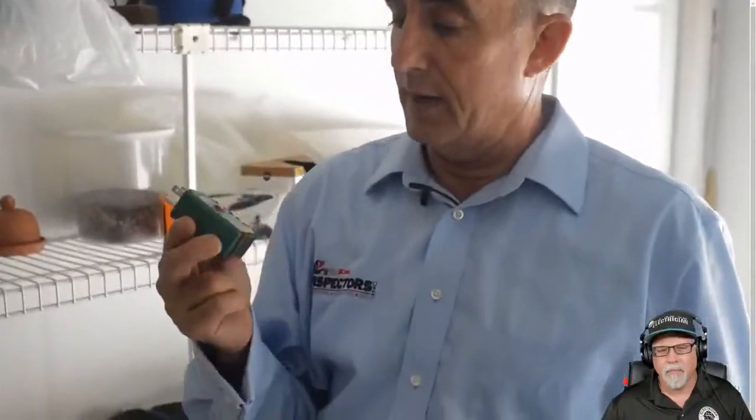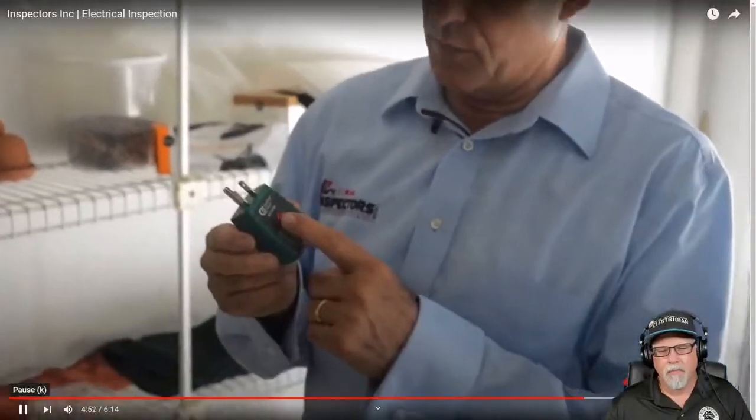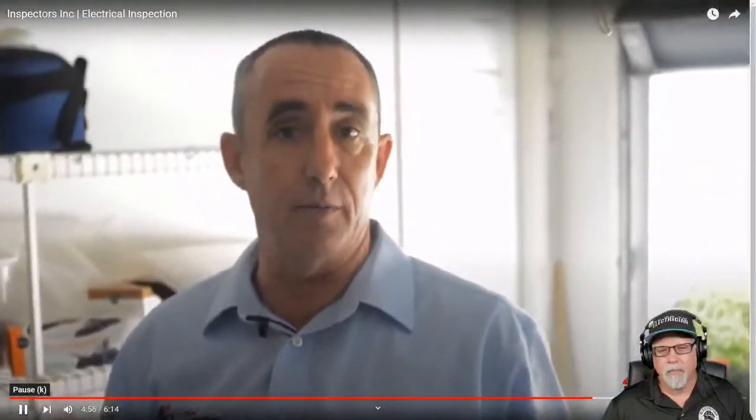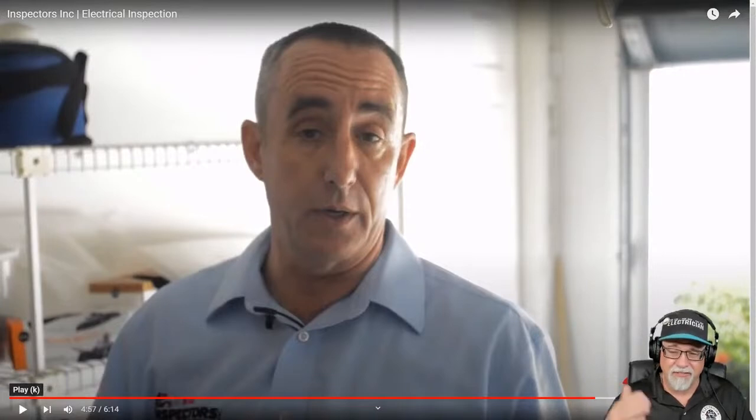Okay, so the next thing in the electrical system that we check is the actual appliances, or the lights, the outlets, the switches. And one of the things I wanted to show you, this is a really neat device, this little trade secret. These you can get at most hardware stores. They're outlet testers. You want to get the one with the little button in there because it tests what's called GFI, ground fault circuit. So it's actually GFCI rather than GFI. So it's ground fault circuit interrupter tester.